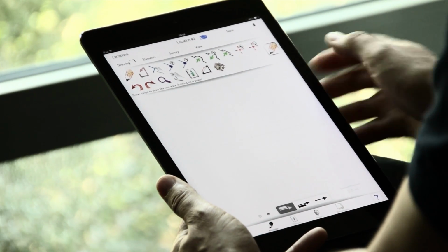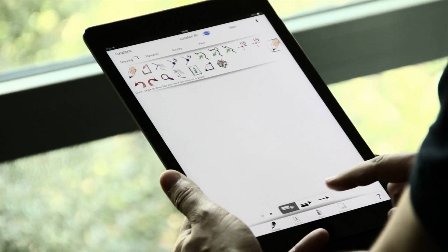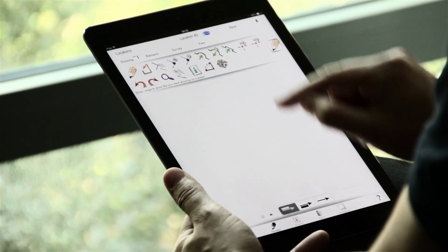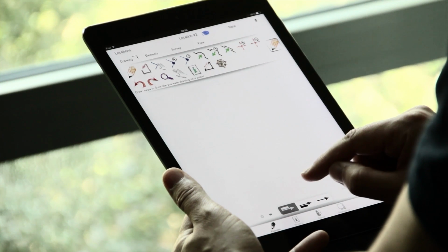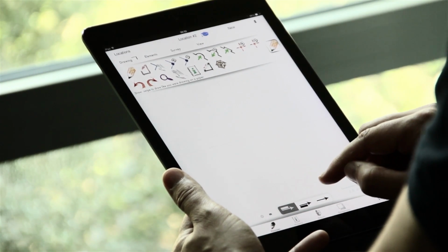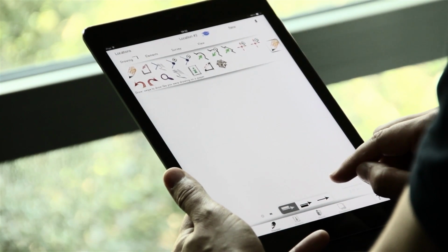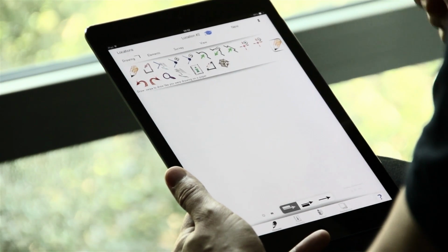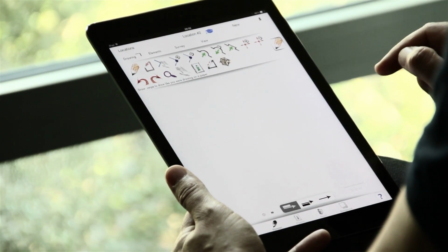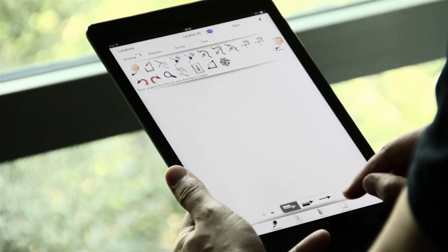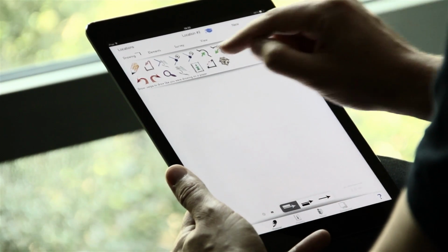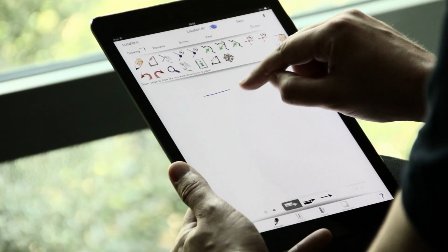And next to it we have the reference line settings. The first option means that the reference line is going to be on the inside when I draw clockwise. If I have that setting, but I'm going to draw the room counterclockwise, then the reference line is going to be on the outside. But if I want to sketch a room without walls at all, then I can go with the third option. So I can just sketch a room and there are not going to be walls there. It's good if I just want to calculate the surface areas. Now let's just go with the first option and let's just sketch the room like this.